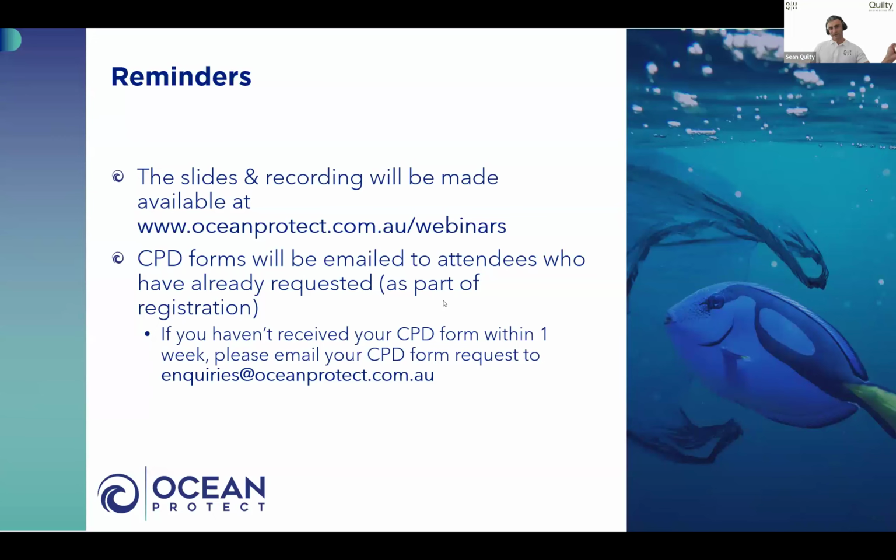The smoother surface means a high velocity, so erosion's an issue. The really high rough surface means depth's going to be an issue. And then if you design your channel for both those cases, then you know you're safe.